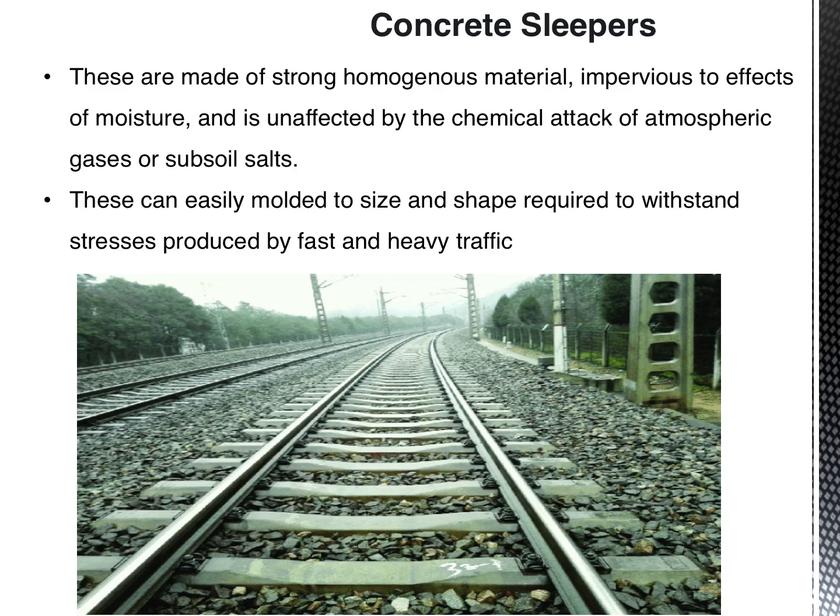Okay, and then it will be impervious to the effect of moisture, and it is unaffected by any chemical attack. There is no corrosion, no decay, nothing. Atmospheric gases cannot decay your concrete sleepers, and subsoil salts will not affect the functioning of these sleepers in any way. The manufacturing is also easy, because concrete can be easily molded to the required size and shape, and it can also withstand the high stresses produced by fast and heavy traffic.